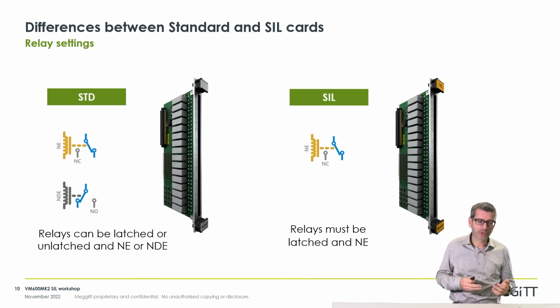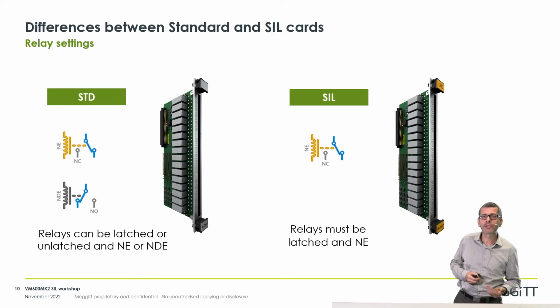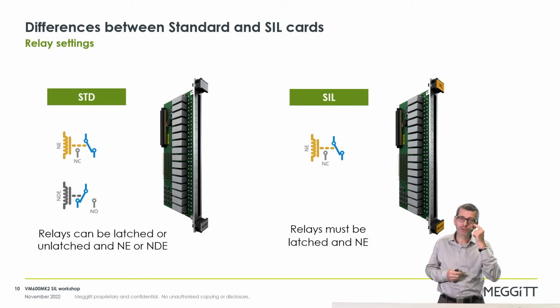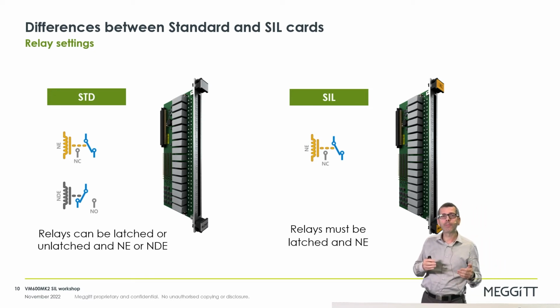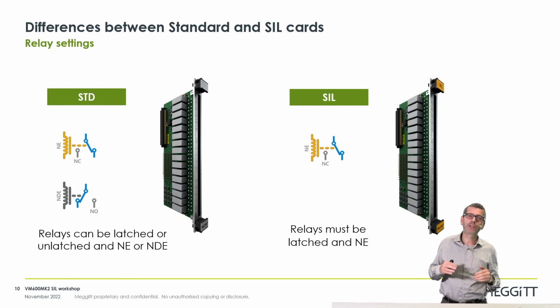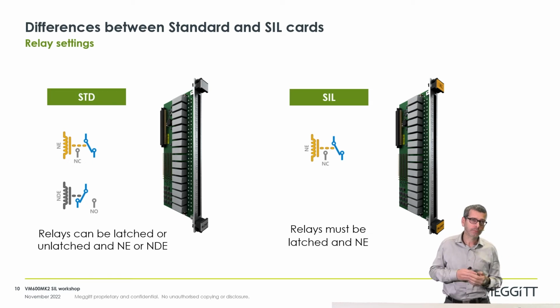There are restrictions on the SIL side regarding the configuration of those relays that apply to the remote relays on the RLC16 and also to the local relays on the MPC4. In a standard card, we can decide to configure them as normally energized or normally de-energized, and as latched or non-latched. The SIL certification imposes that the relays have to be normally energized and have to be latched. So there is no other choice in the vibro-meter protect software for the SIL cards.